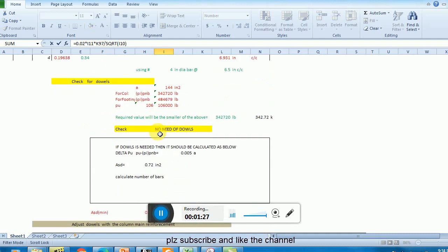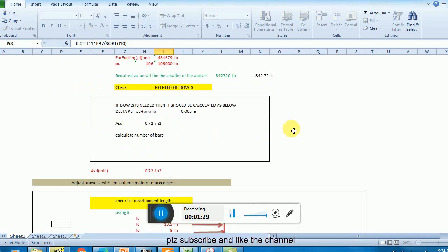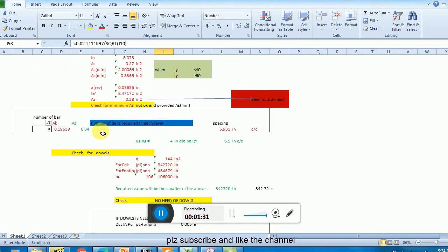The diameter of the bar is 0.5. So first of all we need to find the diameter of the bar. How do we find it? This is my area. The area equals pi d squared by 4, so the diameter is the square root of area times 4 divided by pi, which is 3.14.